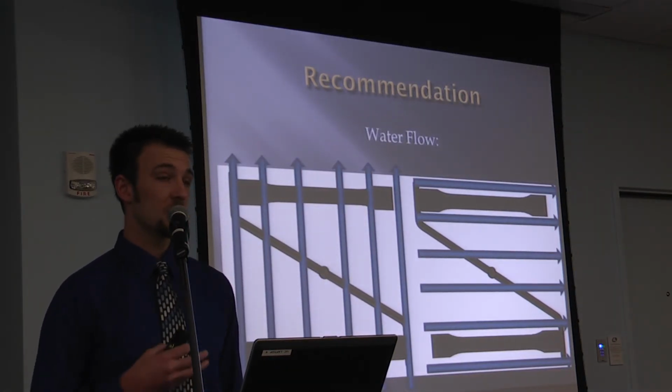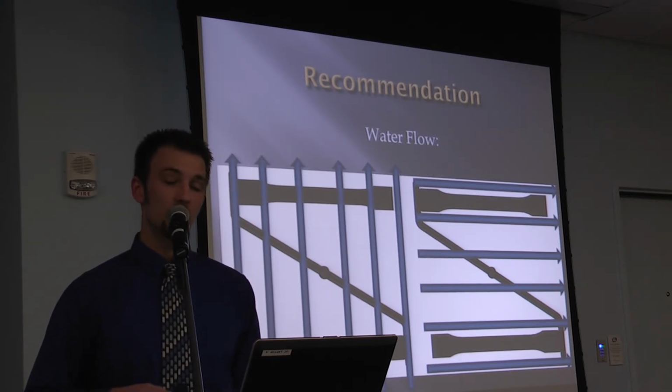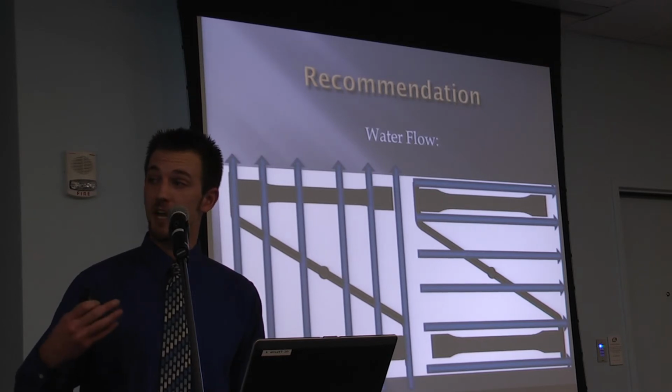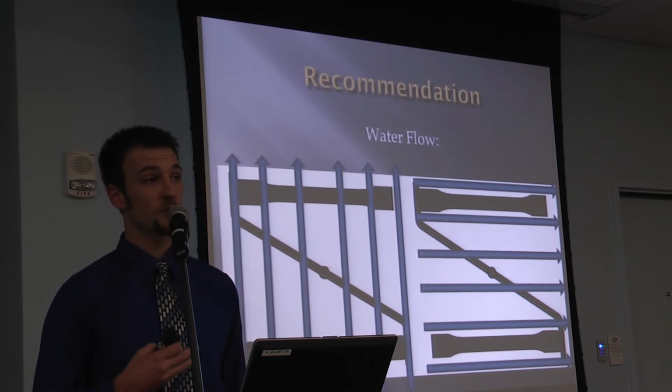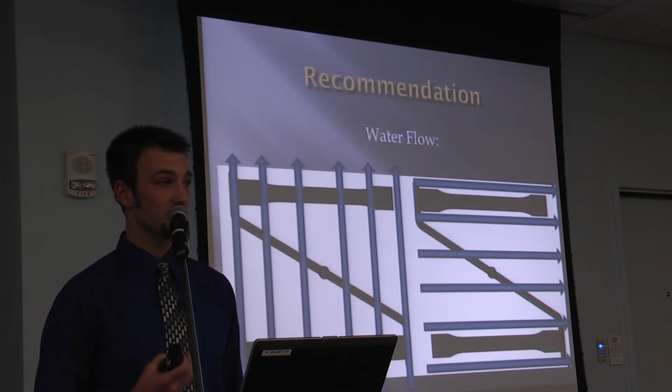Water flow will need to go from bottom to top on one side of the mold and from left to right on the other. We want the water to flow from bottom to top to ensure that no air is trapped within the lines, which can cause the water to be restricted. If the cooling is restricted, cycle times will increase, which will cause processing issues, as well as drive the amount of production down.